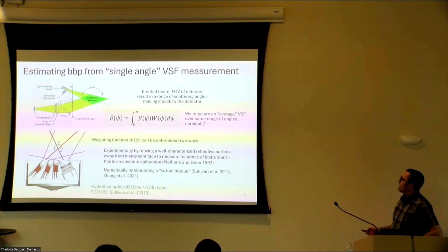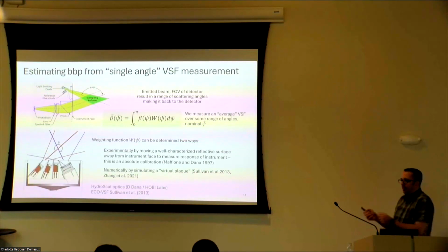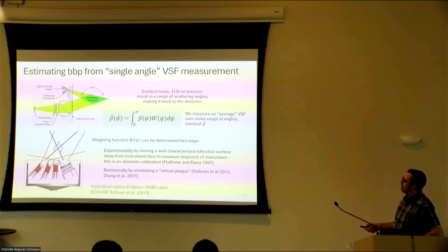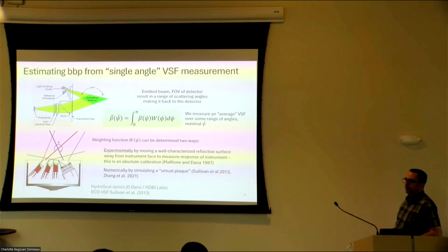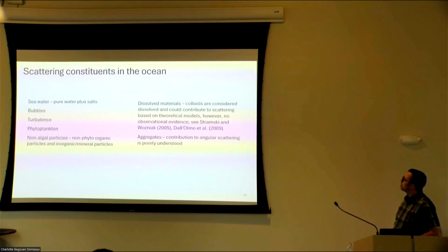So you've limited the field of view of your receiver to be much tighter, and the LED, there's still no lens, but it's a little bit narrower emission. To make that happen, you tend to have the windows a little bit further separated, or make the optics way smaller to get them closer together. So you've got a path length here that's longer than here. Here you're able to get the source and the receiver very close together, which does have some advantages versus a longer path length, but at the expense of not knowing your central angle very well.